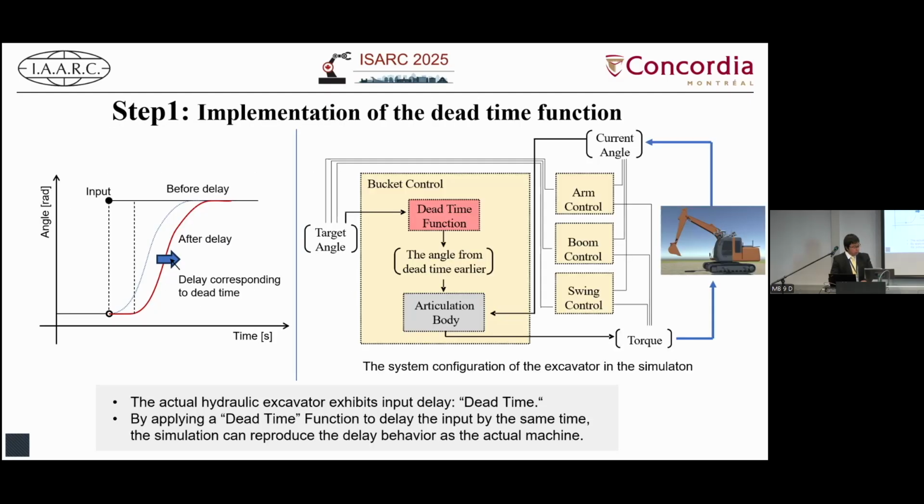The actual hydraulic excavator has a dead time from input signal through hydraulic system to joint motion. By applying a dead time function to delay the input by the same time, the simulation can reproduce the delay behavior of the actual machine.